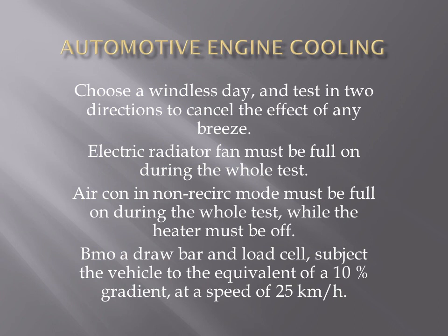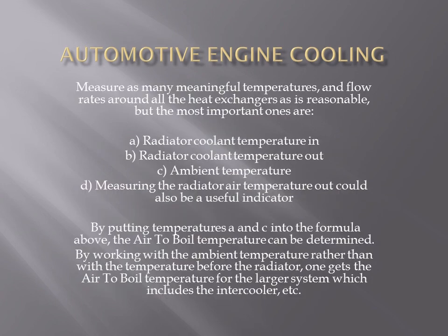The electric radiator fan must be full on during the whole test. The aircon in non-recirc must be full on during the whole test, while the heater must be off. By means of a drawbar and a load cell, subject the vehicle to an equivalent of a 10% gradient at a speed of 25 km per hour.